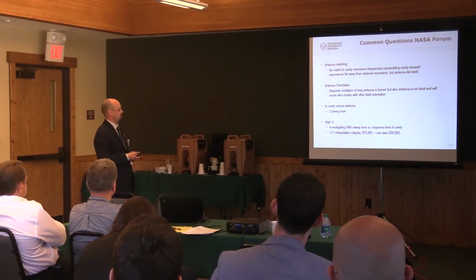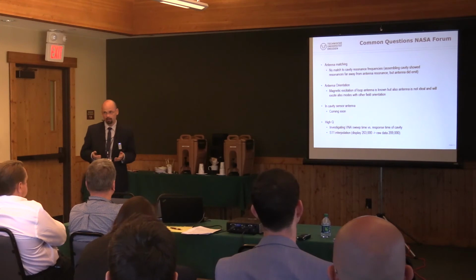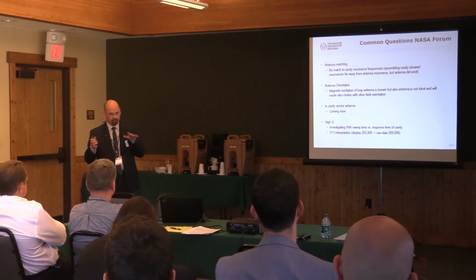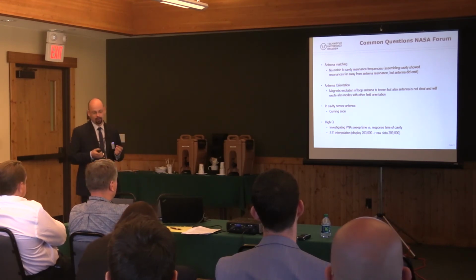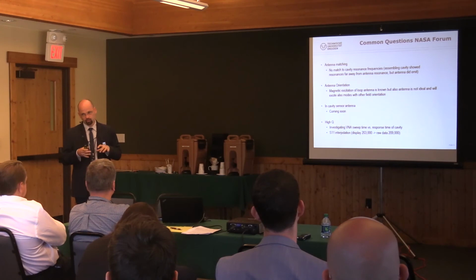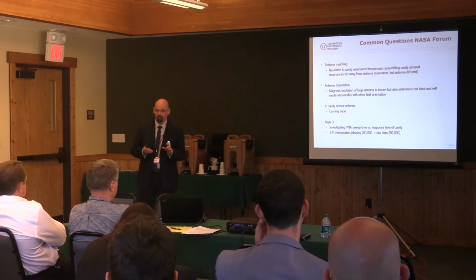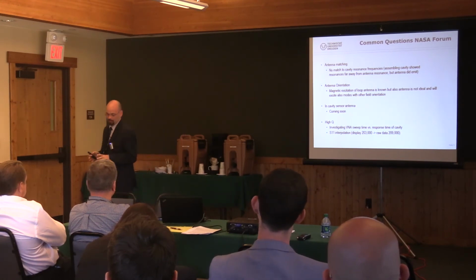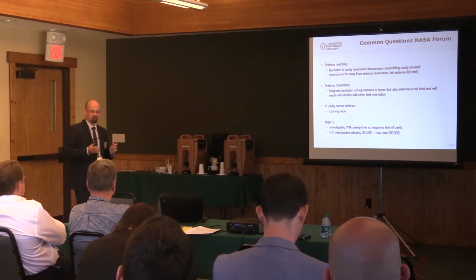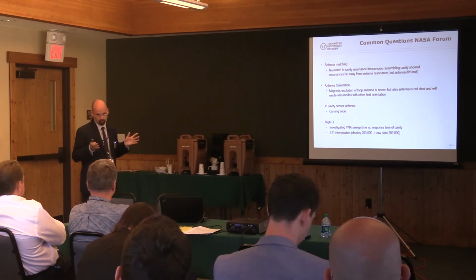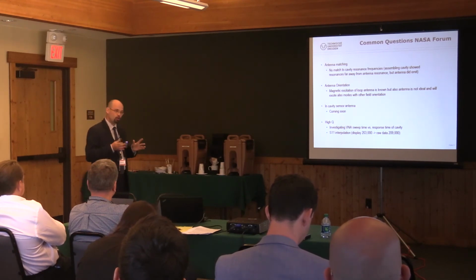Well, talking about antenna orientation, yes, of course, a magnetic loop antenna is most likely to excite magnetic fields, and if you want to excite certain modes, it would be very good to orient and place the antenna in the right direction and the right position. But antennas, especially if they're handmade, are not that exact and not that precise. So a loop antenna oriented for, let's say, a mode TE012 or so, could excite a mode TM212 if we hit the right frequency. It wouldn't be that perfect, the Q factor wouldn't be that good, but we could excite other modes also.